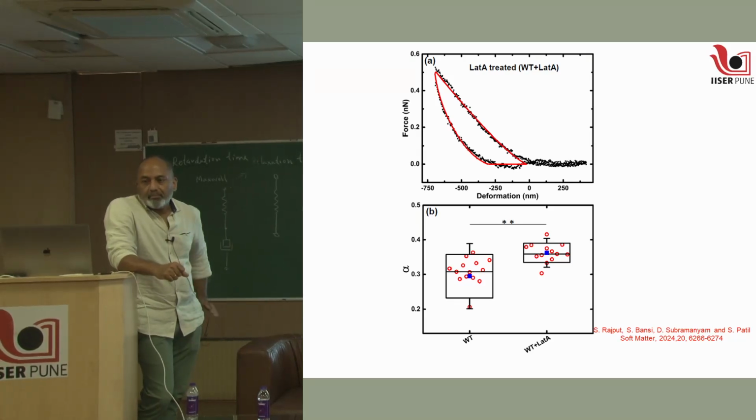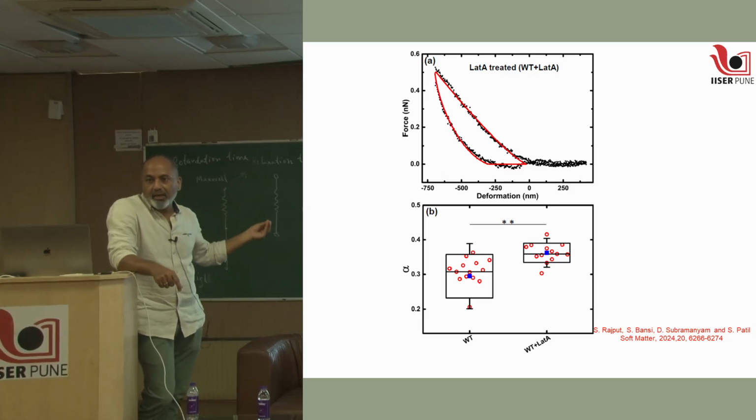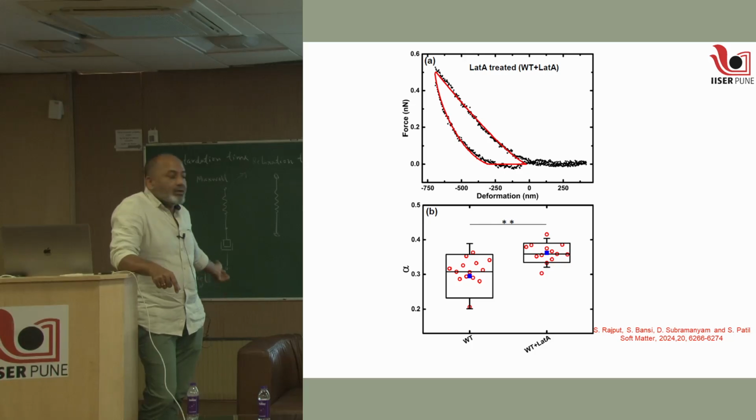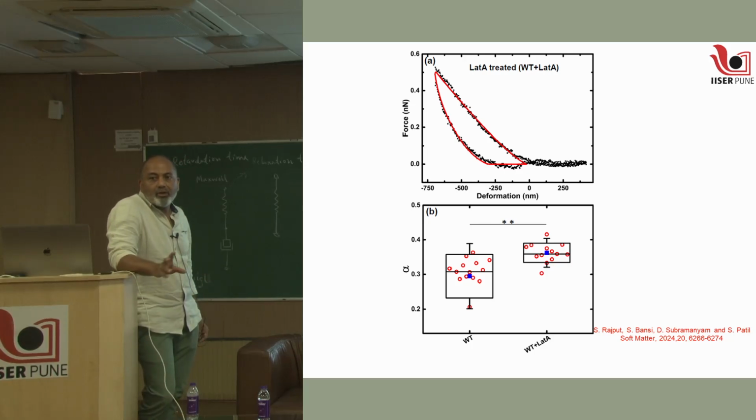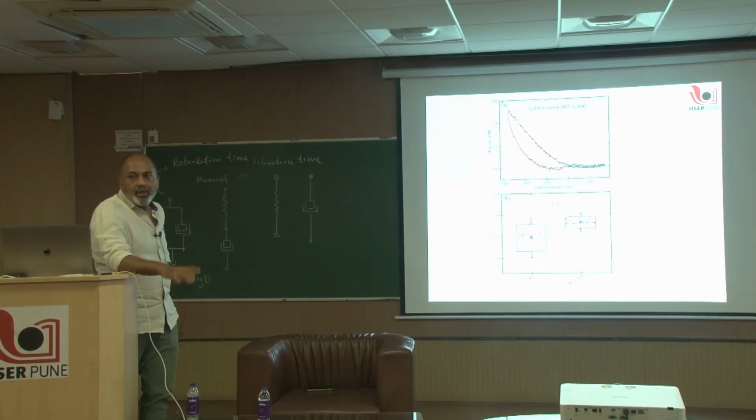For uniform hydrogels it would be fine. But if I'm varying my stiffness, like a gradient gel, then you do this at various parts. AFM has the spatial resolution. You can do this with a small bead or even a tip, and do this at different spots. Each one will give a different time scale of relaxation, because they are not power law behavior. Gels don't follow power law. They're much simpler than that. It's just a single exponent. Thank you.